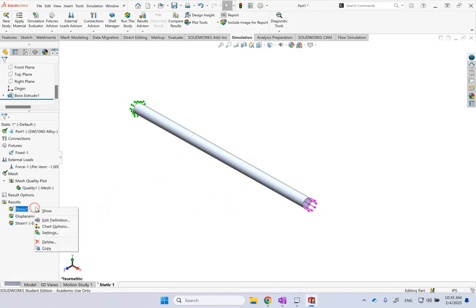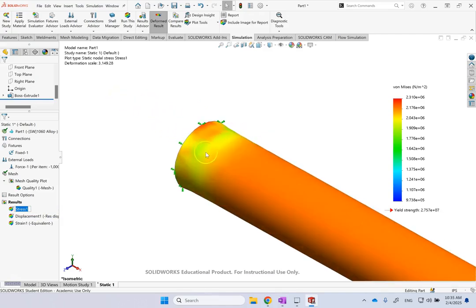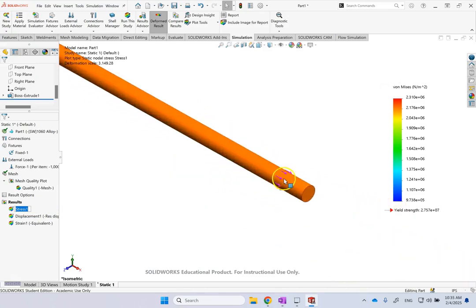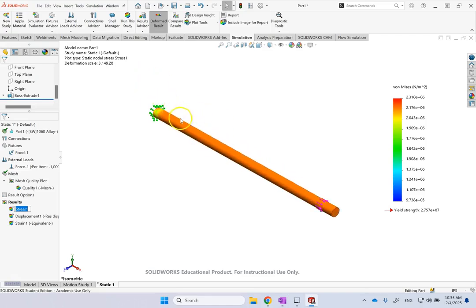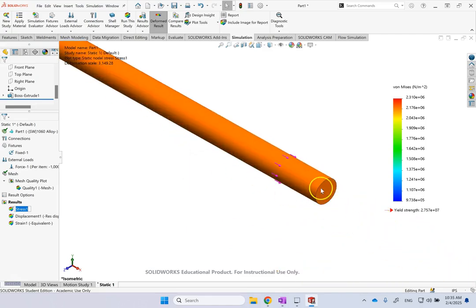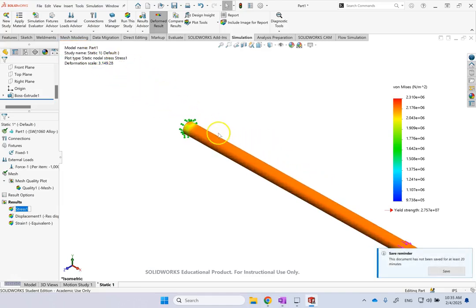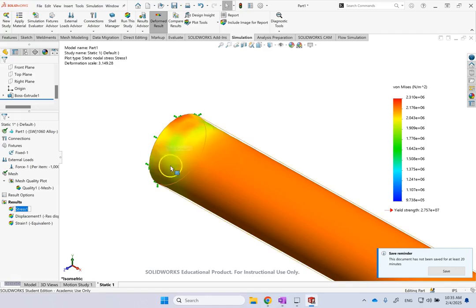If you look at the stress, you can see that around the location of the fixture, or at the other end, the stress distribution is not uniform. Here, this is not a local force; I applied it to the whole surface. But if I applied it to a local area on the surface, I would definitely see that the load distribution will not be uniform.